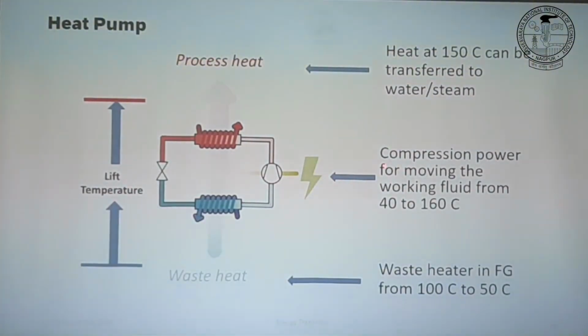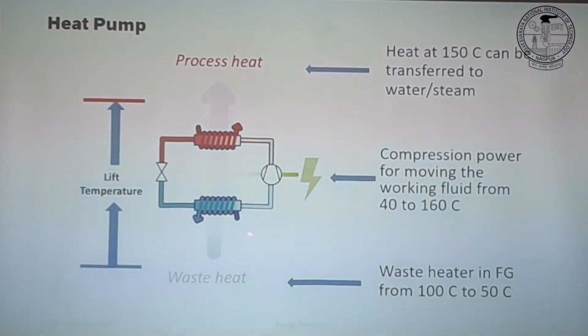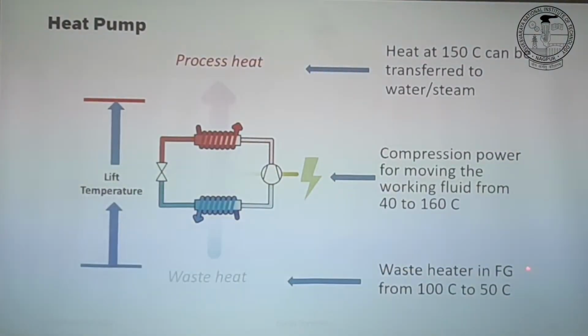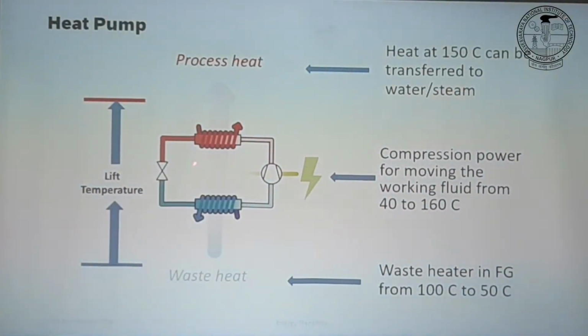So the form of energy we are putting in here is running this compressor. You see 100 to 50, that means my organic fluid must be vaporizing at 40, with a 10 degree temperature difference.